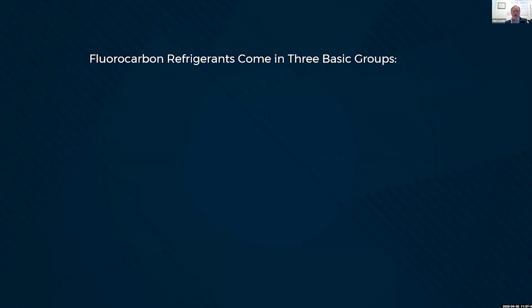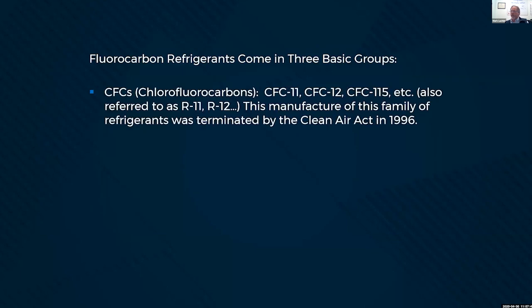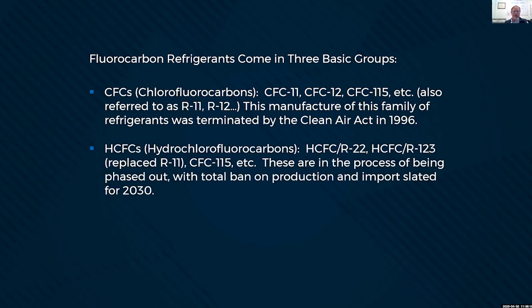They come in 3 basic groups. The CFCs, which are kind of the granddaddy, R12, R11. Some of us still remember those. Those were phased out in 1996. It's no longer legal to manufacture or import them. They were replaced by the HCFCs, the hydrochlorofluorocarbons. So that's your R22s, R123. They are being phased out as well. We're not going to be able to make them or import them after 2030.